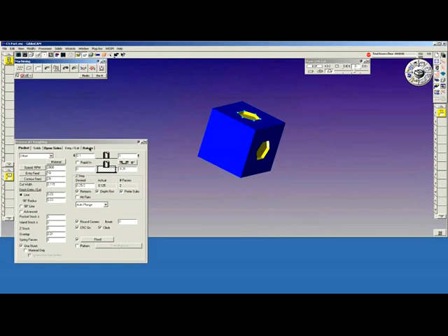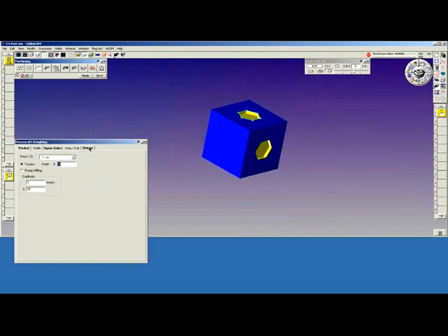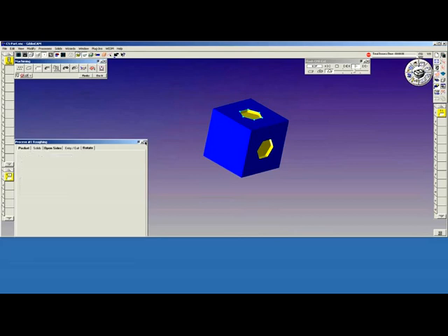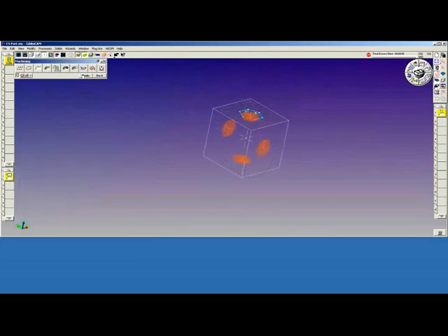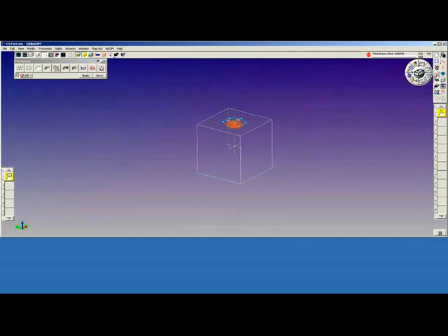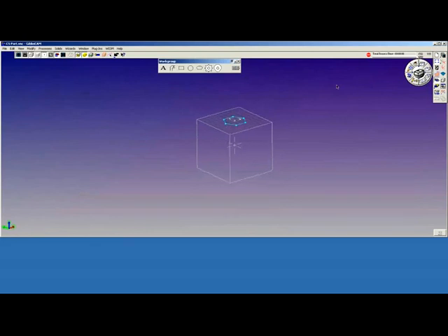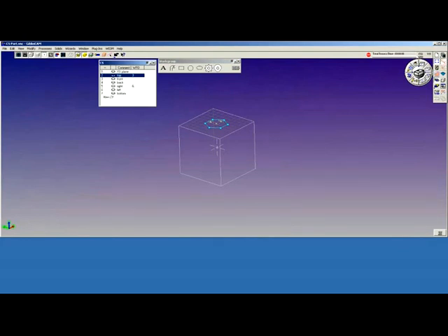Okay, I'll go back to the Rotate tab and make this 0 once again. Close this and redo it. For subsequent machining, I'm going to turn off my tool list and cam list, and I'm going to draw some more geometry. To get the geometry, we change coordinate systems. We go to the front.